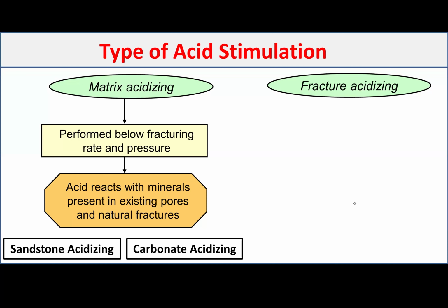So matrix acidizing is simply pressure and rate less than frac pressure, and two types: sandstone acidizing for sandstone formation, carbonate acidizing for carbonate formation.